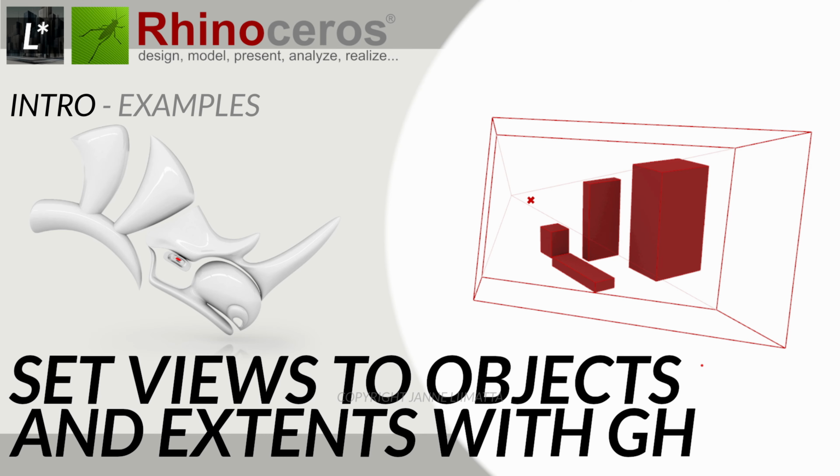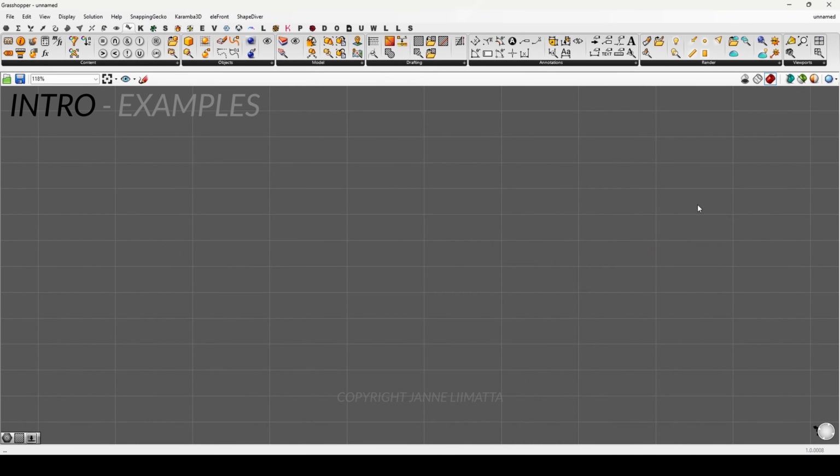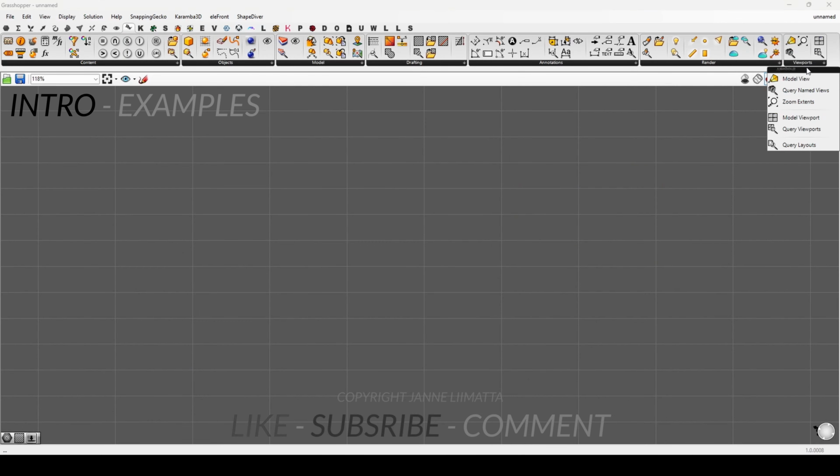Hello! After watching this video, you will know how to create and set named views in Rhino and use the query named views and zoom_extends Grasshopper components. The latter can be used to set views to individual objects too, so make sure you watch the whole video. These components can be found in the Rhino tab's viewports section.